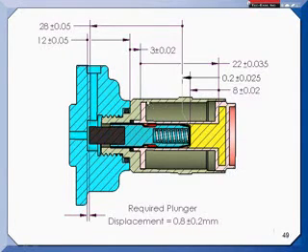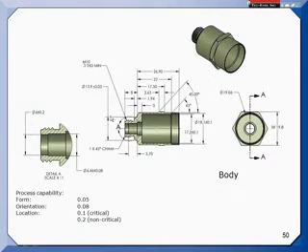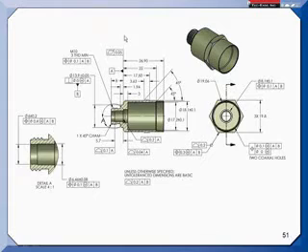Now if we look at this part, it's going to pilot on this diameter, and it's going to mount up against this surface right here. So when we look at the completed drawing, when you tighten up the threads, there's enough clearance, and it's a coarse thread, that when you tighten it up, you do make full contact here on that surface, and it does allow you to center up. There's a real nice fit here between here and the casting. So that becomes my datum feature B, and that's all I needed for this part.